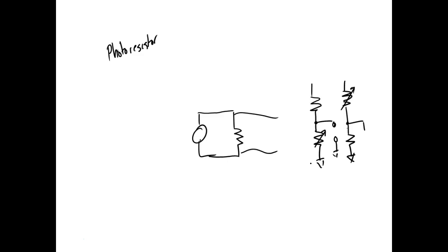But at whatever it's trying to measure, it's still going to have a resistance. So it would always give us an output voltage. It allows you to establish zero. It allows you to do any other things to set references. So now it means something, right? So now we can make it mean something. So we put it in a bridge, and then we can calibrate it.